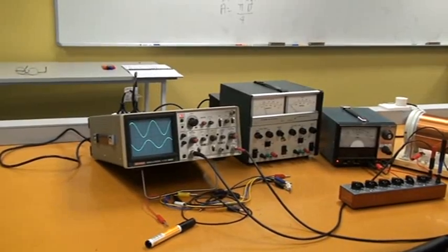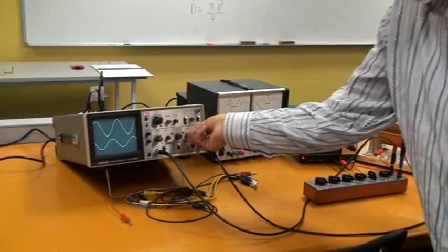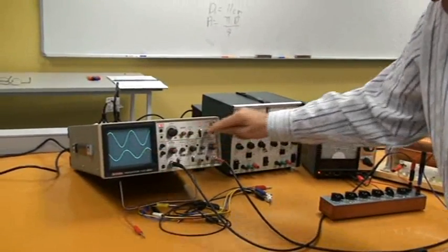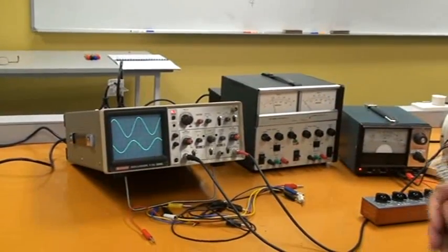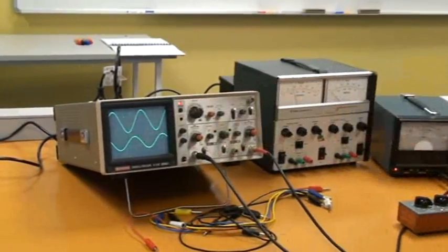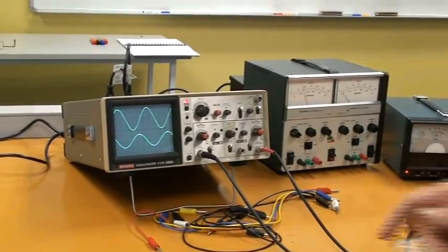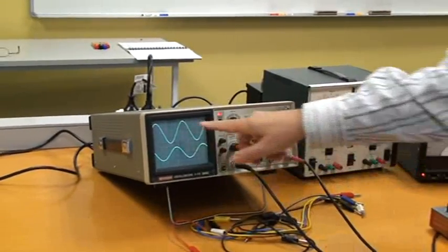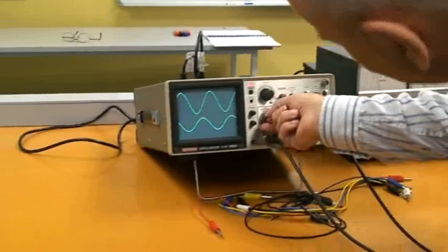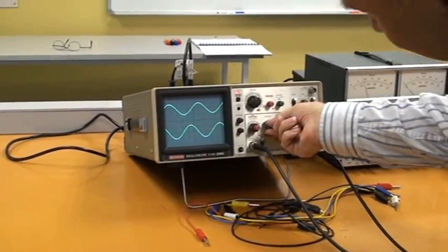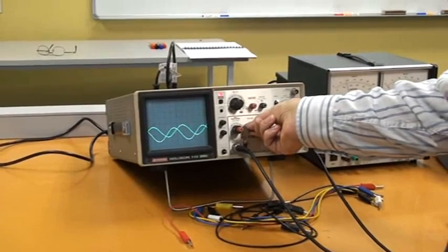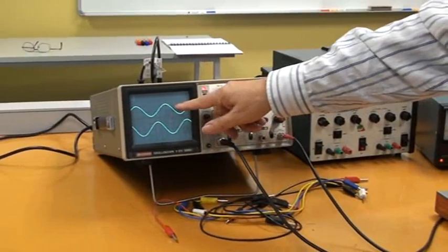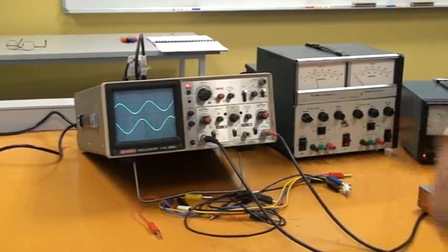Now remember how we measure voltages from an oscilloscope. We must look at how many centimeters there are, and here it's about 2 centimeters peak to peak. Now 2 centimeters times the range on here, which I need my glasses to see, I think it's 1 volt, so that's about 2 volts. So the voltage across the resistance is 2 volts. And the voltage across the coil is about 3.5 divisions. Let's go to 1 volt per centimeter, that makes it easier. And that's about the same actually, which it should be. That's how I designed it to be. So we've got about 2 volts across the resistance and 2 volts across the coil. So those are the measurements that we've made.